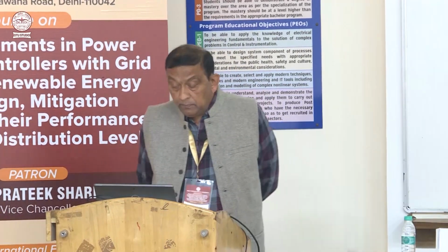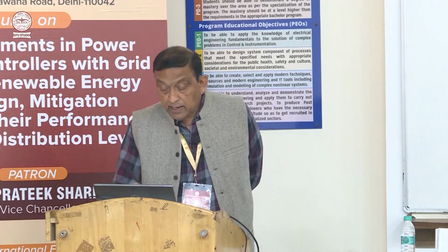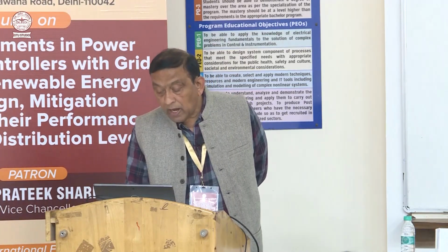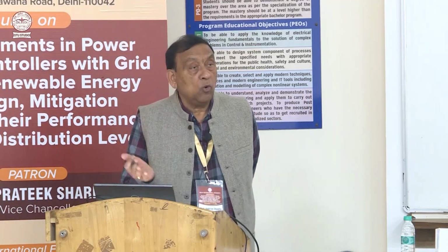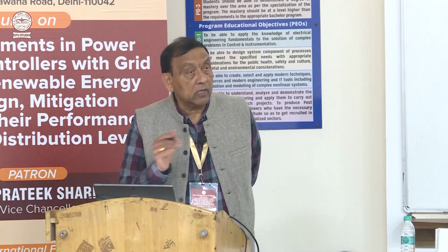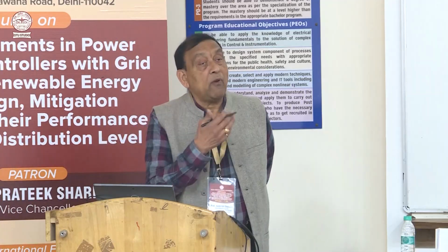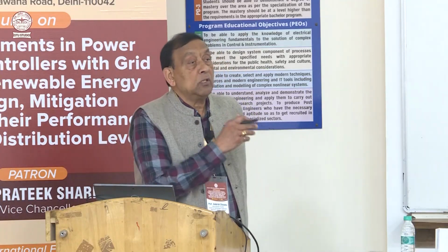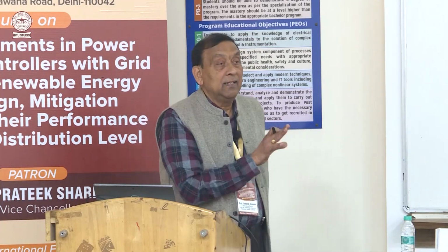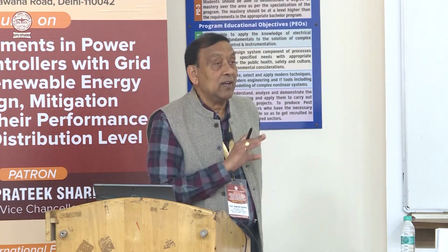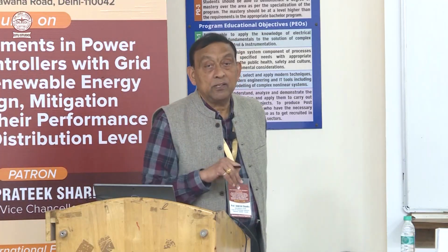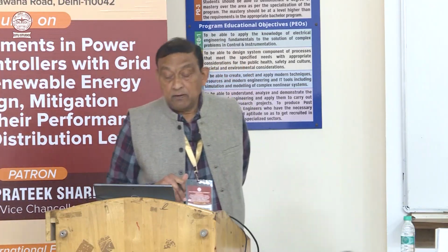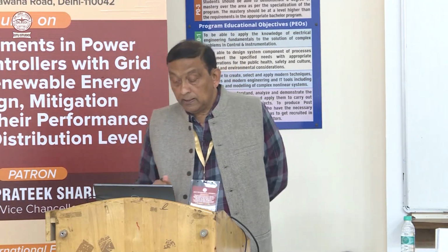And then PMSG has enhanced fault ride-through capability. Low voltage ride-through, high voltage ride-through, or fault ride-through. So it has capability. Why does it have capability? Because you have full-size back-to-back converters. The converters totally decouple the generator from the grid. So that's why it has that fault ride-through capability.